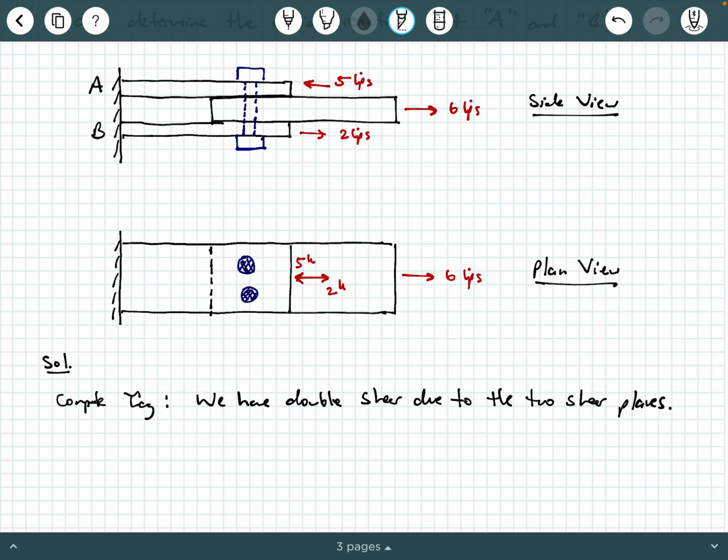So one thing that we like to remind ourselves of, and it's really from statics, is applied loads on a system. What do they try to do? They try to take the path of least resistance to get to a reaction, to get to a support. So for this 5 kips to get to a support, the path of least resistance, we sometimes call that the load path, is right through the top plate. Similarly, the load path for the bottom 2 kips is right through the bottom plate.